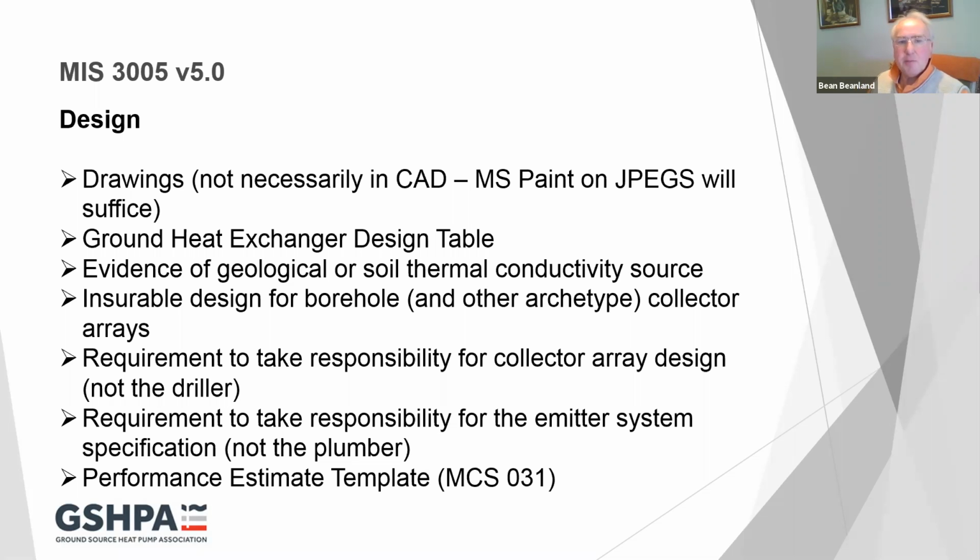There's a requirement to take responsibility for the collector array design. So even if it's not a subcontract, there is still a requirement on the MCS certified installer to be responsible for the design of the collector array. It is not appropriate to get the driller to work out how many boreholes are required. That is not MCS compliant. And there's a requirement to take responsibility for the emitter system specification. Again, underfloor heating, radiator sizing, what have you, not the plumber.